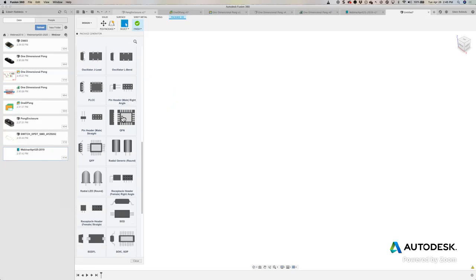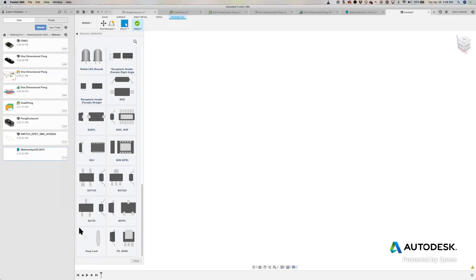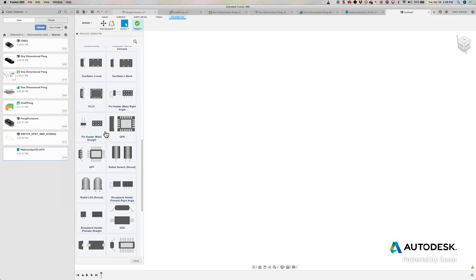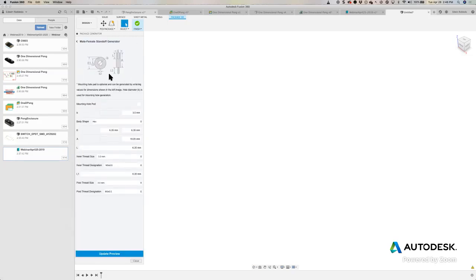And then there is the nylon connector, if you're going to be attaching a circuit board to another circuit board. And here's what you're going to see on the circuit board. Of course, it's going to just create the hole, but you will get this 3D model as well. Once you select it, based on the specification sheet wherever you're buying them, just type in the measurements here. The same actually happens with the standoffs. You tell it the type of thread it has, and it will just build it as well. As you can see, I experimented with this. I actually did this one, the M3.05, and it gets you that hardware as well.